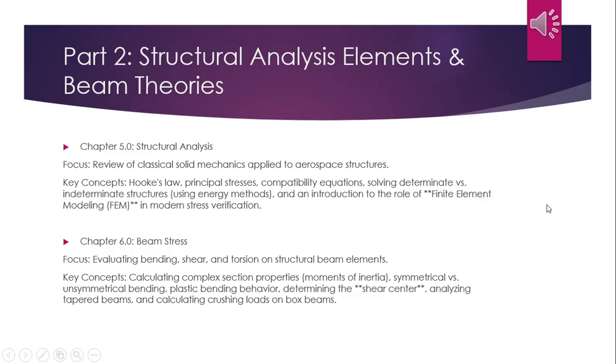Part 2 is about the structural analysis elements and beam theories. Structural analysis focuses on a review of classic solid mechanics applied to aerospace structures. The key concepts are Hooke's law, principal stresses, compatibility equations, solving determinate and indeterminate structures using energy methods, and an introduction to the role of finite element modeling in modern stress verification. That's chapter 5, structural analysis.